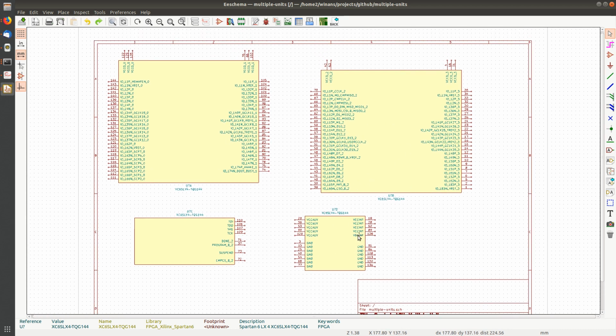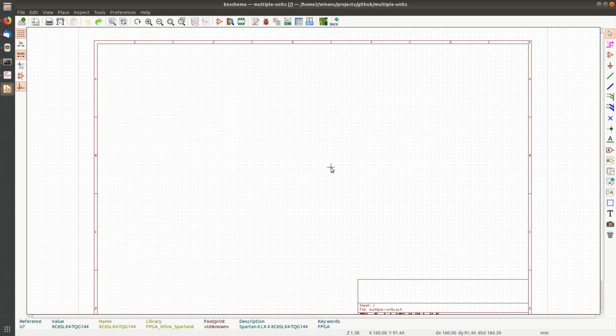There's no pins there for it to notice are not connected. So number one, make sure you put all the units down if you're going to work with these things. Otherwise, your DRC won't work. So this is one kind of multi-unit device where each unit is unique and has different roles and different numbers of pins and even different shapes and sizes. So I'm going to Control Z and get that guy out of there.